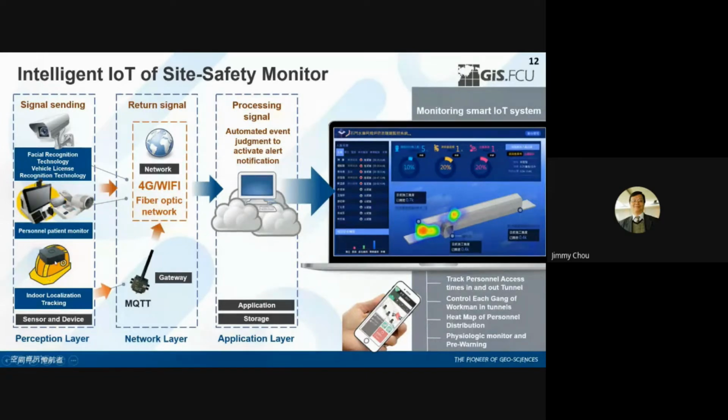Once the movement of the worker shows, for example, after 10 or 50 minutes, there is no movement, or he has possibly fallen down, which means it's over a certain elevation for certain minutes, then the sensor sends a signal back to someone in charge of the construction site security to send out an alerting signal saying, okay, this worker might be in some trouble, so you had better take a look, or just call him to see if he can answer back.